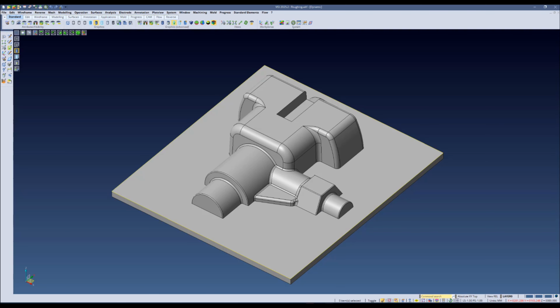Thank you, Chandler, for the great info. My name is Wesley. I'll be going through some of the changes to the Workplanes over the past few versions. The first thing that I want to go over would be the datum down here in the bottom left corner. If you right click on this, this will give you a couple different options to manipulate your workplane. There's an option to reverse Z, transform workplane, create workplane, and your workplane manager.